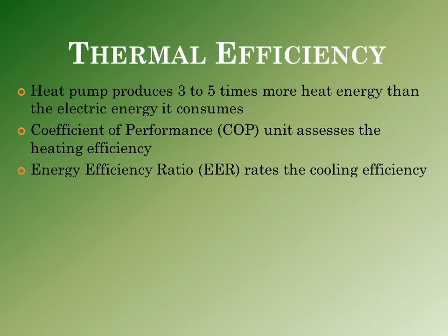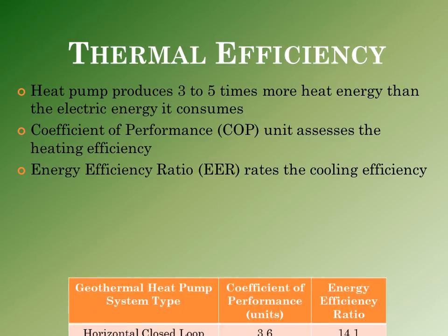A heat pump moves 3 to 5 times more heat energy than the electrical energy it consumes. To determine the thermal efficiency of a geothermal heat pump, we use the coefficient of performance and the energy efficiency ratio. COP is used to evaluate the heating efficiency. EER is used to rate the cooling efficiency.